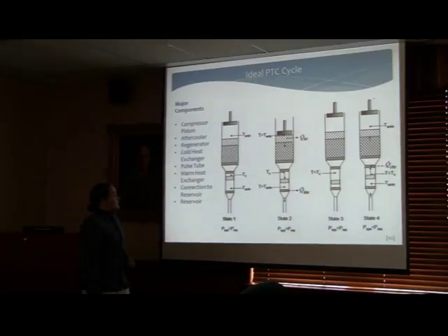So what happens is that the compressor piston is going to push down, it's going to heat up the air, and raise the pressure to be larger than the system, like the reservoir. Then some of the heat is going to escape through the aftercooler, which is what it's supposed to do, and the rest is going to be held in the regenerator. So the pressure went up, and then at a shifted time scale afterwards the flow is going to move down.